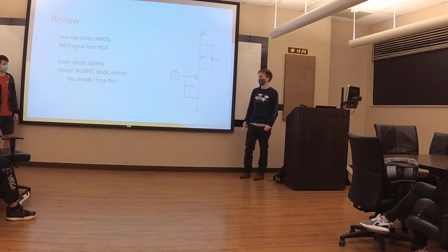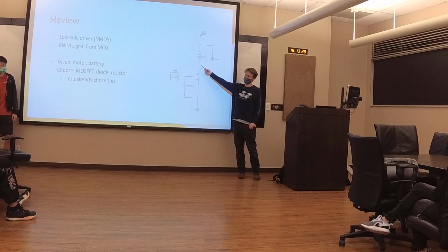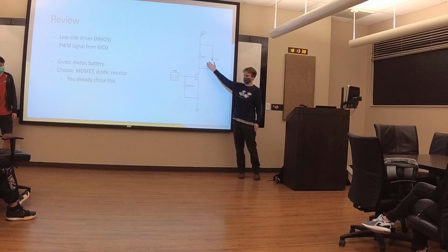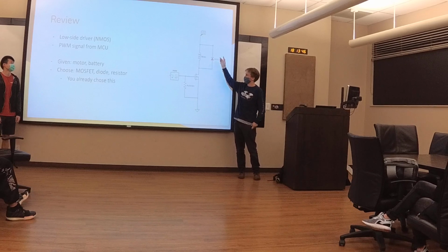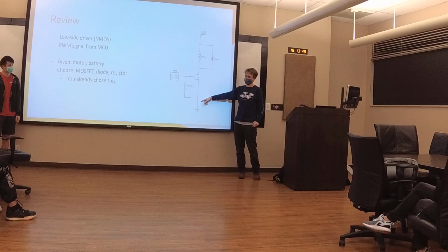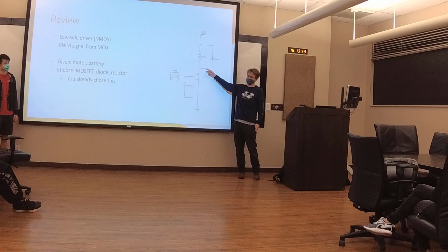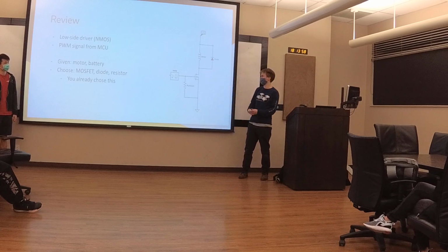The other thing that I want to add is that the motor is not a sensitive electronic component, so it doesn't matter that it's not directly connected to ground, so we can get away with doing this. If you add something like an op amp right here, which if you don't know what that is, stay tuned for EE11L, you're going to use those there, you want that to be connected directly to ground because it uses ground as a reference. A motor doesn't care about any ground references. All it cares is that current is flowing through it, and that's why we can get away with this.